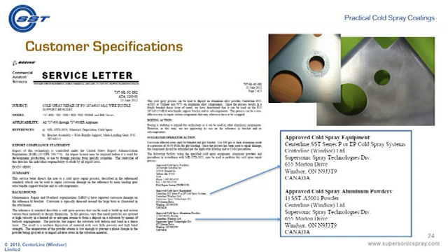Now, within the service letter, I've expanded the areas where you can see where the approved cold spray equipment is: CenterLine SST Series P or Series EP cold spray system, and below that is our approved cold spray aluminum powder, SST-A5001. Now, for those of you in our audience who require specifications in order to utilize a repair process, you can count on us to help you develop that internal specification.